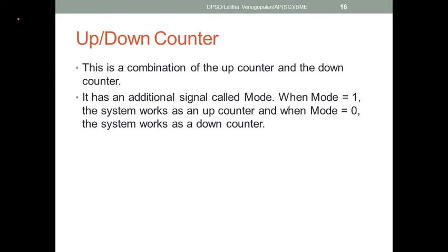So like I said, you can use the same circuit as an up counter or as a down counter. It just depends on whether you're feeding the input to the next stage through Q dash or Q, right? Whether the set pin is used to give the input to the subsequent stages or the reset output is used as input for the subsequent stages distinguishes whether a counter is an up counter or a down counter.